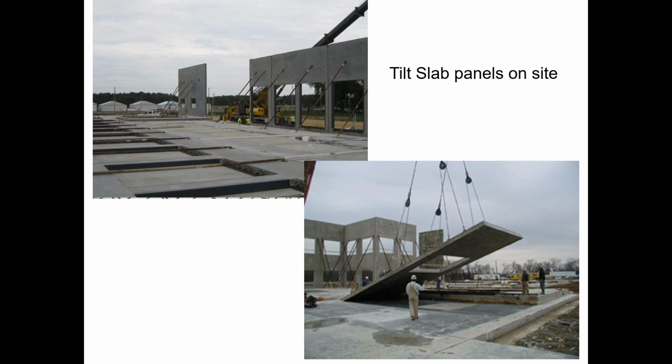Now I'm going to bring up something because a lot of you like to leave this in the raw concrete state. There's nothing wrong with that. And Rob will go over it later. But if your MPa is above 30, and that's the concrete's been dense enough and all been done correctly, then that stops water going through it. So you don't necessarily have to paint it. You can paint it for cosmetic reasons or other reasons, but you don't actually have to paint it for weather tightness. But Rob will talk to you about that later.